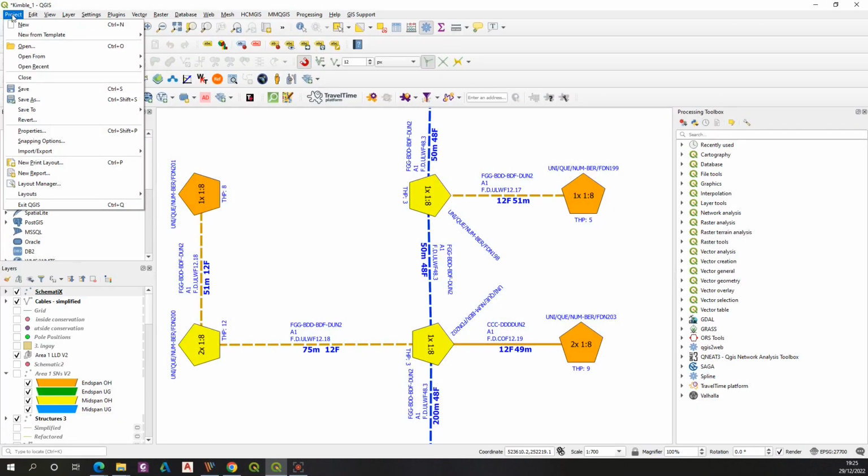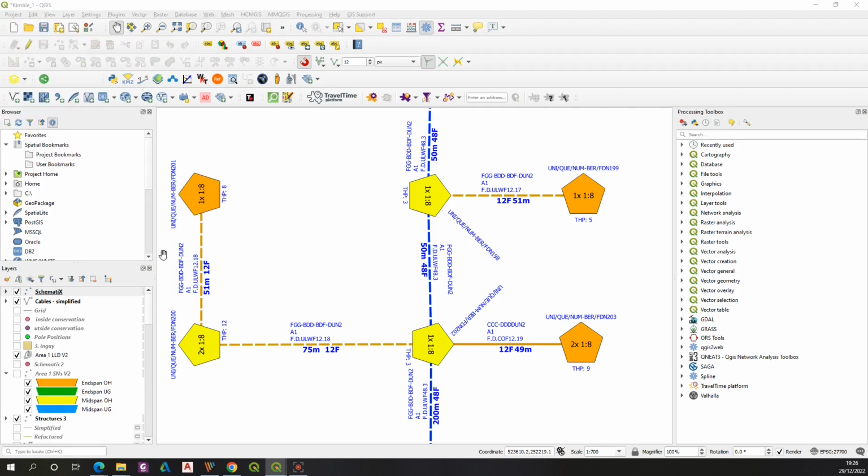The PDF document for this purpose can be generated from the print layout in QGIS. I assume that you have some print layouts already available in your project. However, maybe not necessarily for this type of drawing, which reflects the infrastructural location of objects rather than the map with layers itself. But I have some layouts available here, and one of them is dedicated to the straight line diagram, which has already been prepared earlier. I can use it, but I would like to explain all of the steps of how a print layout such as this, this particular template, can be generated.